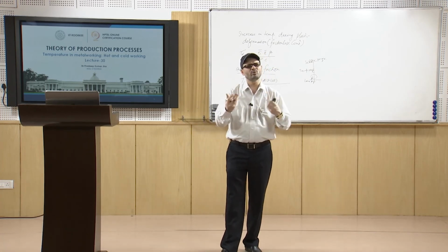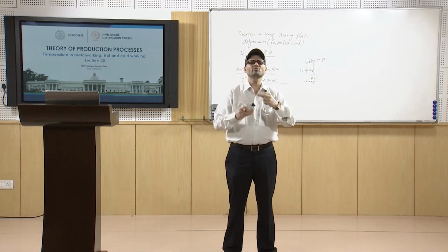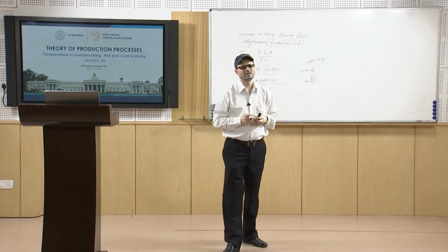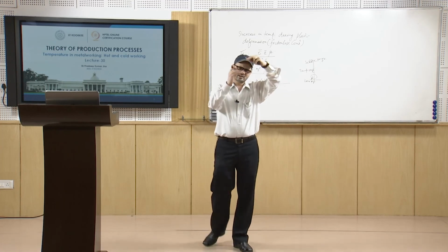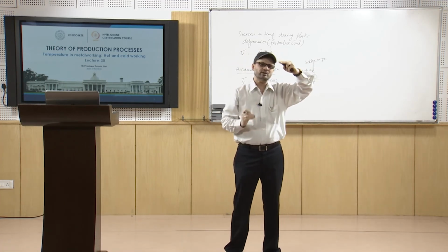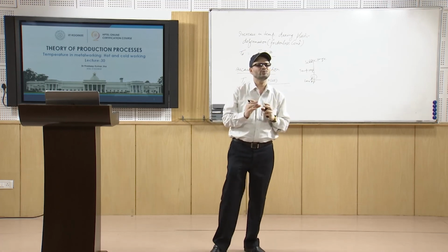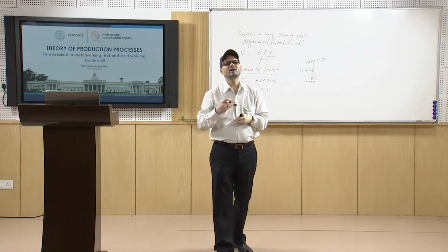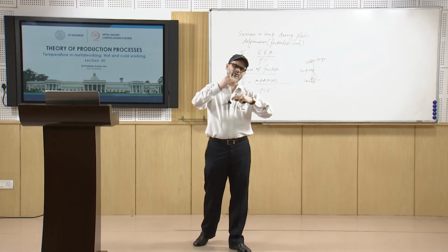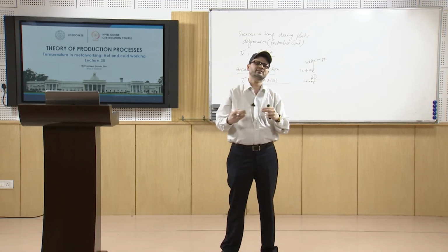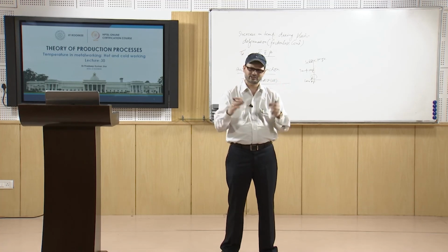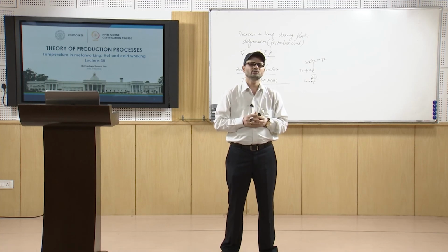Apart from that, you also have the warm working process. Warm working is basically in between; it takes the advantage of both cold working as well as hot working. It goes below the workable range in which recrystallization occurs in hot working, and then comes up to room temperature. So, it has the advantage of both hot and cold: less load, and then less wastage because of oxidation. It is in between those temperatures. So, this is about these temperature effects in the case of metal working.